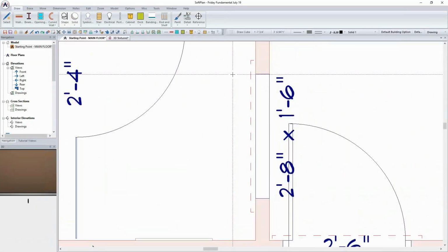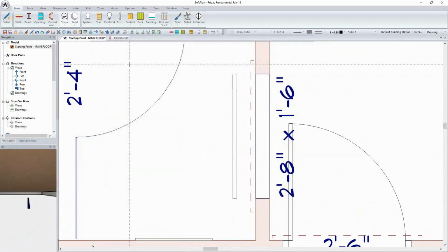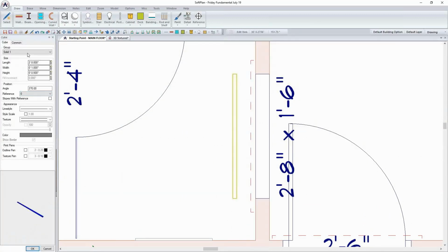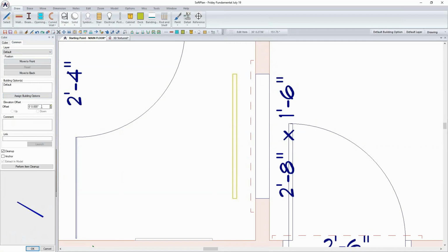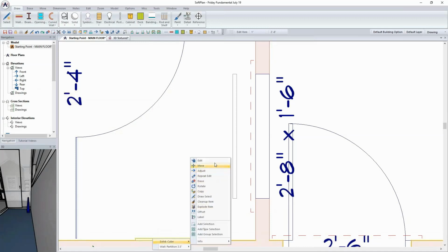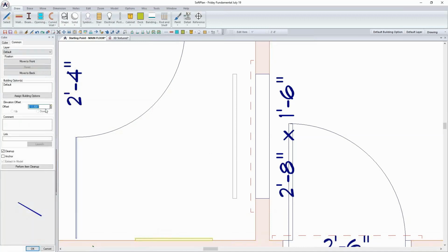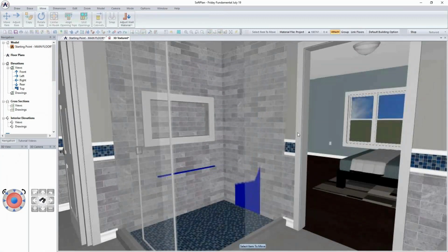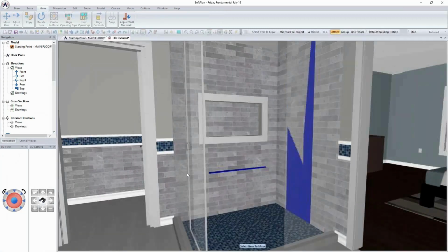Now these cubes, keep in mind, I'm using this to do a design pattern, but the cube itself has no bill of materials whatsoever. So there's no soft list flag for this. I'm going to offset this up 3 feet, and in this case, this cube I'm going to give an offset of 11.625 inches and a height of, let's say, 7 foot 8 inches. And now I've added these two cubes to the drawing.